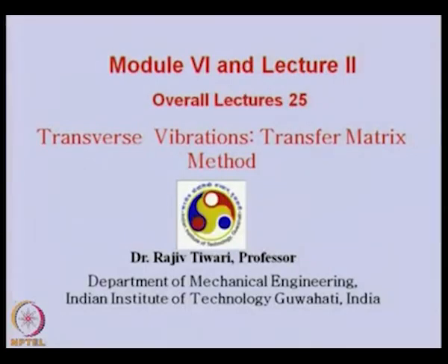Today we will study transverse vibration using transfer matrix method. This particular method earlier we studied for torsional vibration case. We have seen the advantage of this method, that this can be applied to multi-rotor system, and we have seen that this particular method, once we develop the point matrix and field matrix for the disc and the shaft, we can use this for larger system also.